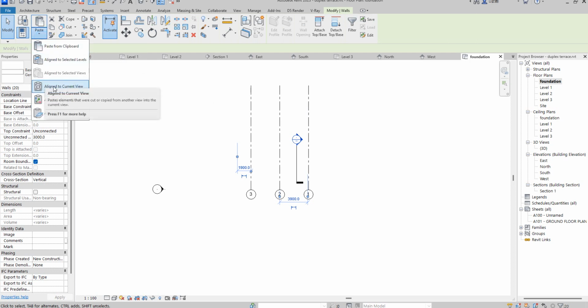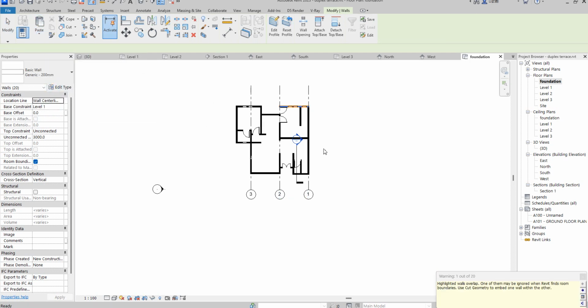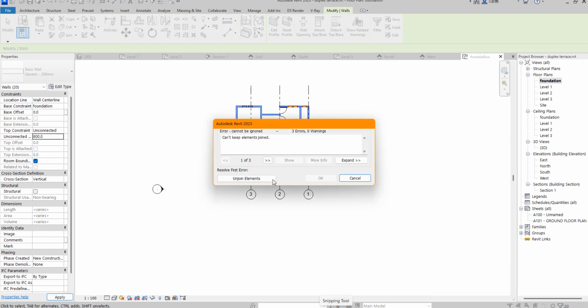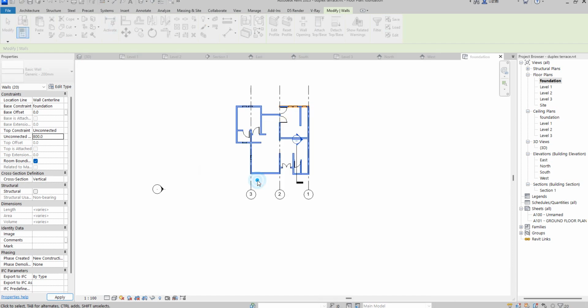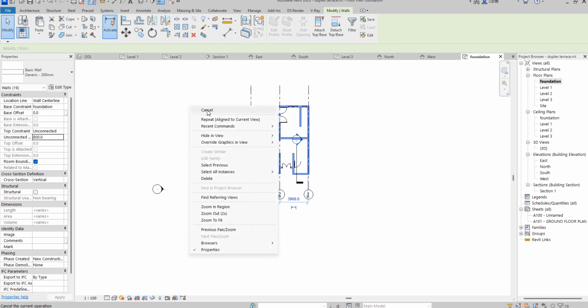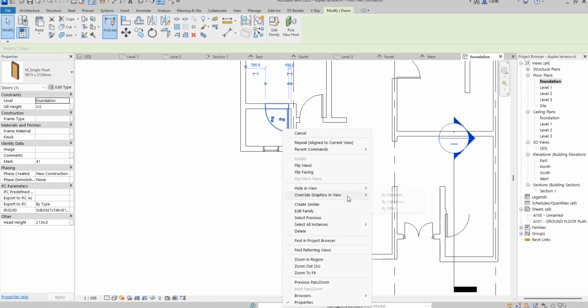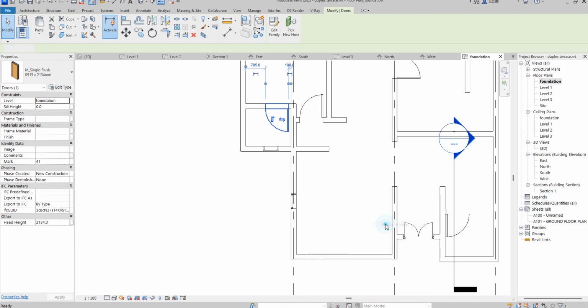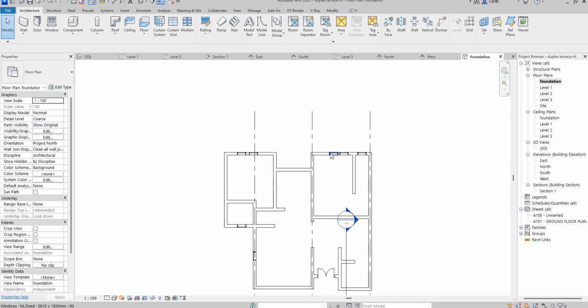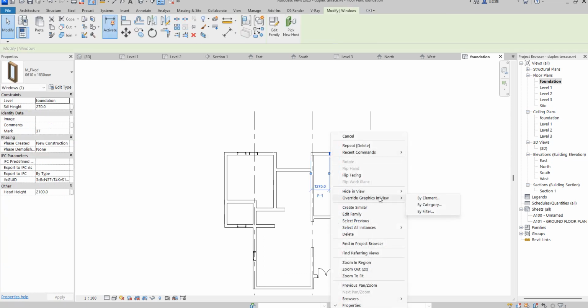From here now, say align to this current view. So it's there. So what I then need to do is to adjust the height. So I'm going to say 800. I always use number 1000 as my own. Then I'm joining there. So what I need to select now is to select this and say select all instance in this view. Then delete everything that I have done relationship with that. So select all instance in this view as well.